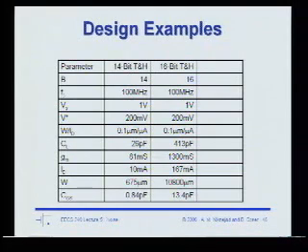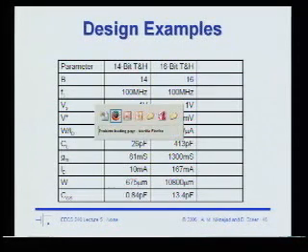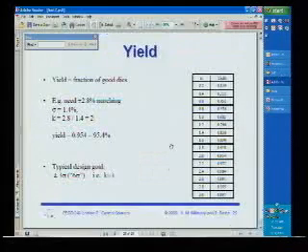The choice changes a lot because as the transistors get faster, you don't really take the speed penalty when you operate closer to, let's say, n times kT over q. Okay. Any other questions?